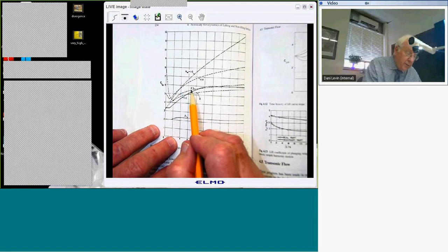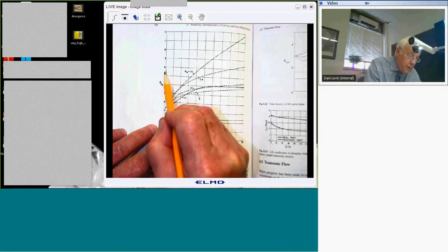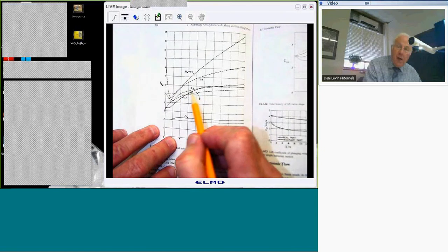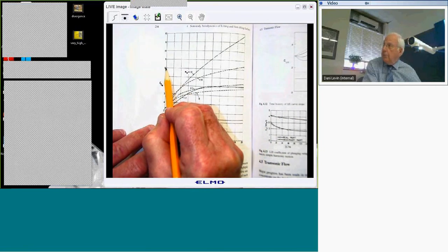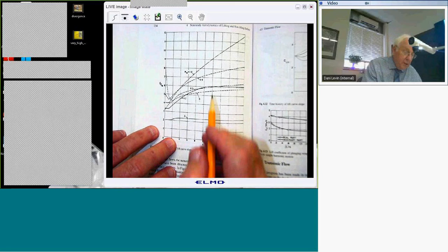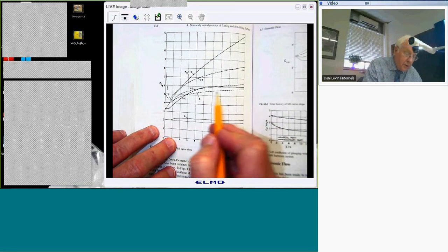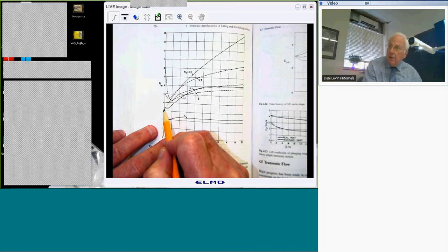And then Mach number 0.5, here's the result. And at 0.5, it should again be 4 over Mach number, should go to 8. It does. By the way, the guy who did this never noticed that that's what was happening, but that's okay. But then, at a Mach number 0, it goes right here, and it goes down to, actually, you can't tell it, but that's a little above 3, it's really pi. Turns out the magic number is pi.